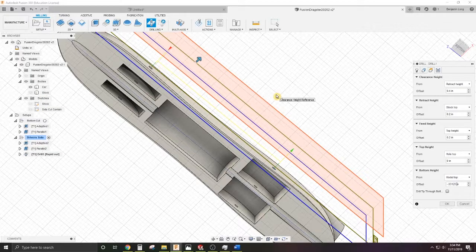And why we're doing that is the diameter of our bit is 0.125 inches. But most axle holes and most axles and bearings that we're dealing with are 3 millimeters. 0.125 inches, or the size of the bit, is 3.17 millimeters. So when you're drilling the hole, it's already too big, bigger than it needs to be. So if we just mark the hole with this bit at 1/32 of an inch, barely down in there, we can come back with a smaller drill bit and use the drill press to drill that hole at the correct size the whole way through. And then from there, we'll know it's perfect and right in the right spot and at the right diameter. And we'll just use that drill to mark that.